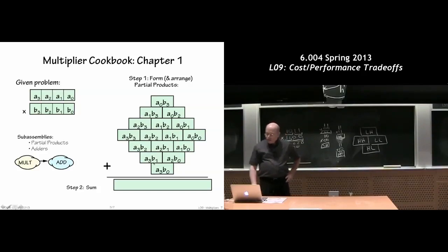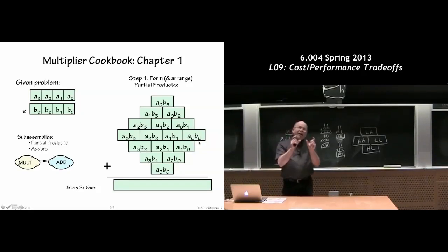Yes? So just to make sure, the rightmost column would be just B0, then after that it would be B1 plus A0 plus B0. No, so this is meant to represent the 2-bit product of A0 times B0. Right, so when we write A0, B0, it doesn't mean the bits A0, B0, it's actually the product of A0 times B0, for some size operands A0 and B0. Does that make sense? Okay.